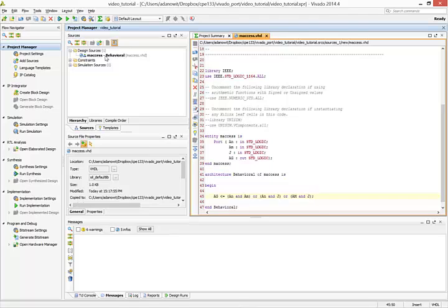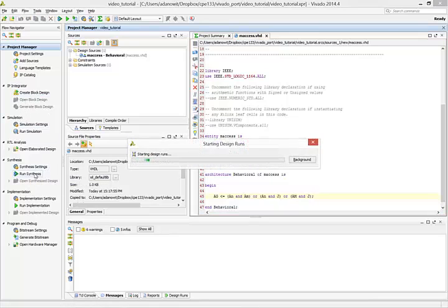All right. Now, if we want to make sure that this circuit works, one thing that we can do is create a test bench for this circuit and simulate it. But doing a test bench is kind of a tricky thing, so I'll include that in the next video. For now, the first step of getting this circuit onto the board is to first run synthesis.